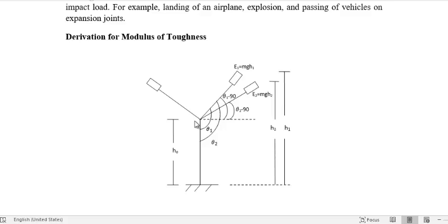So we have a fork in the setup. This line with the end mass is showing the fork or hammer. In the arrangement that we have, one end of the fork is pivoted and that end is here, and the other end is free. And we have a lever with the help of which we can rotate this fork. When we rotate the lever, the elevation of the fork increases, and at a certain height a component that is attached with the fork collides with another component of the machine and the fork gets released, and then it has a free rotation.